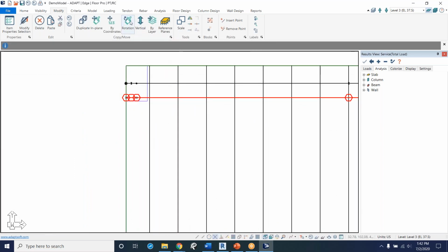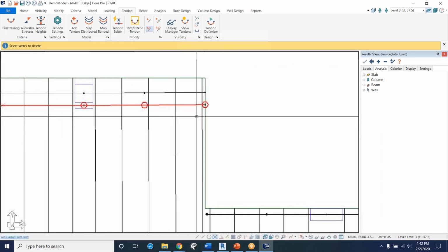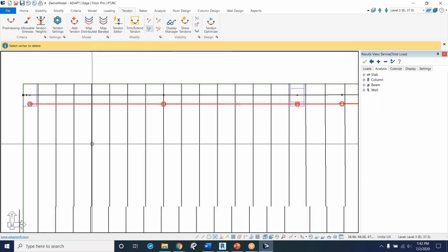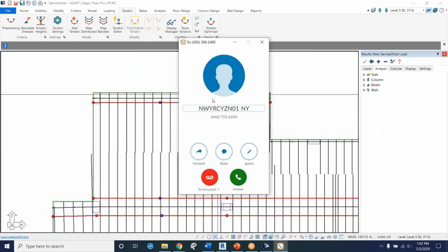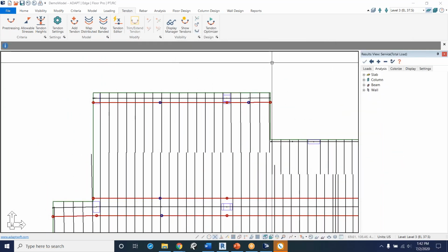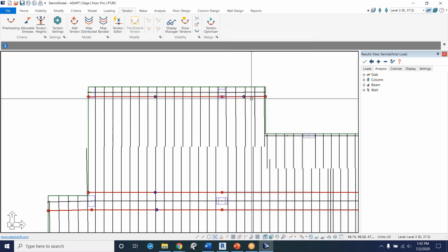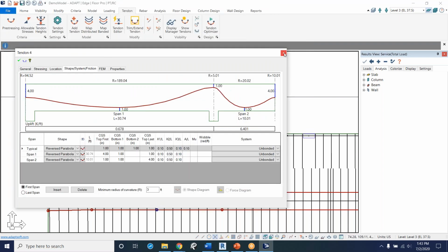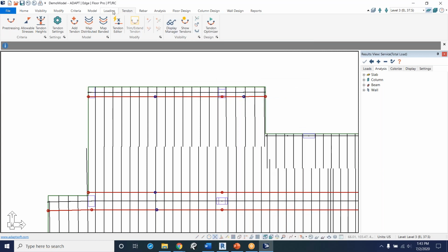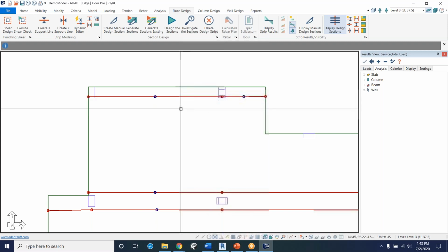We'll clean this one up real quick. Delete this tendon point. That one doesn't have one there. Maybe we want to change that one to cantilever down, but we'll trim extend. Now, we could go into each individual tendon like I showed to adjust the profile. With a lot of tendons, in this case we don't have a lot yet, it's not very difficult, but with a lot of tendons, it becomes a little tedious to individually click through them.